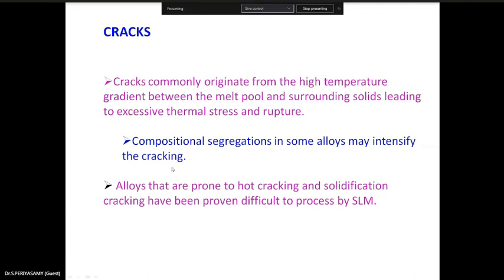Even the unmelted cores are here. So this is a powder bed. The powder bed layers are struck by the beams here. By striking that, you can have either no sintering neck formation. So the neck is not formed. In that case, you have unmelted cores inside. The liquid is not enough to melt the remaining balls, so it will form a circle alone. If the liquid is more, it will form a neck, a sintering neck.